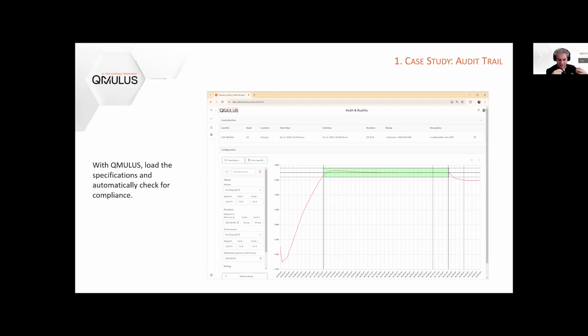Now, what I defined physically is this rectangle, which in this PowerPoint is shown in green. That rectangle was defined by someone with knowledge, someone with experience, and someone that knows the spec. This is the thermocouple needed. It does not need to be the furnace thermocouple, lowest thermocouple, coldest thermocouple, hottest thermocouple, whatever. Pick this thermocouple. When it reaches this point, you start the time. And the furnace thermocouple should not exceed plus or minus this. And your duration is that.